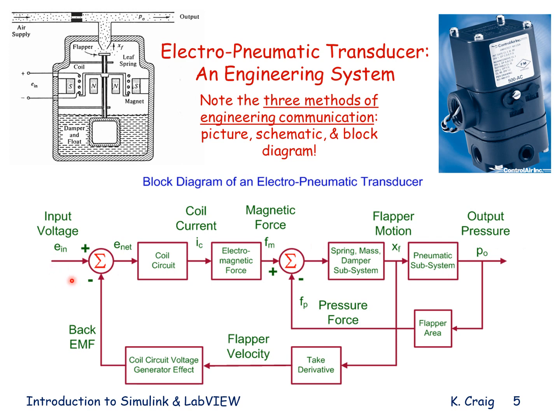The way it operates is that a voltage is supplied from some voltage source. That voltage gets applied to a coil. In that coil, then a current flows. Because that current carrying coil is in the magnetic field of permanent magnets, an electromagnetic force in that coil results. That force is applied to a spring mass damper system. The spring consists of these two cantilever beams, which have compliant springiness and also have some damping characteristic.